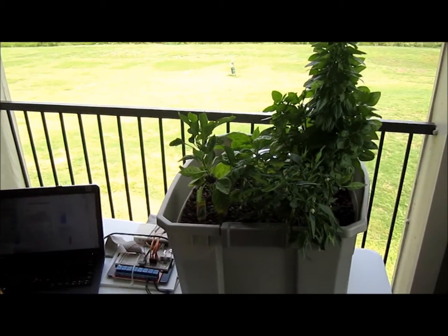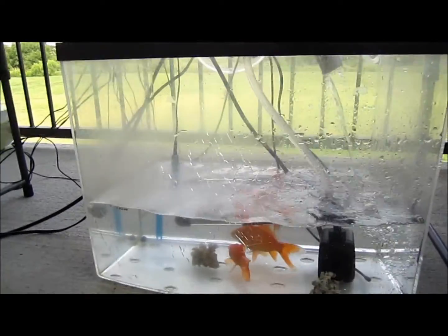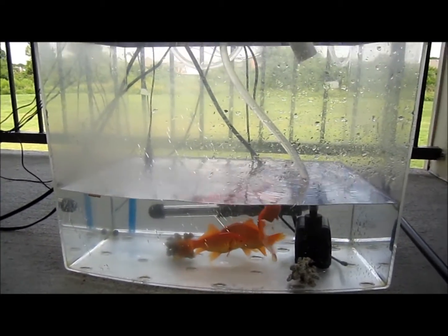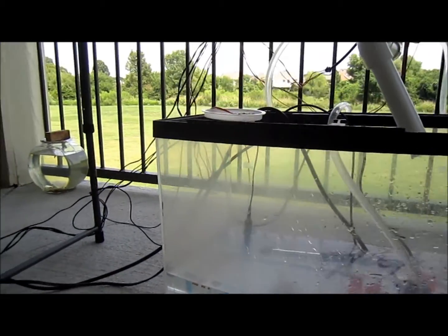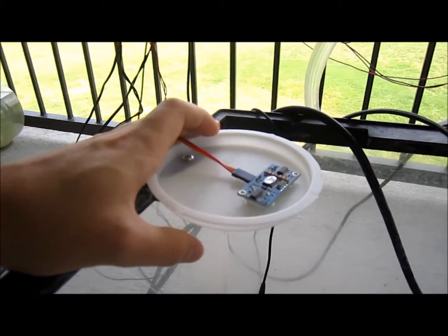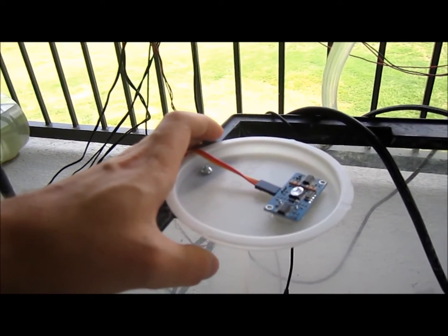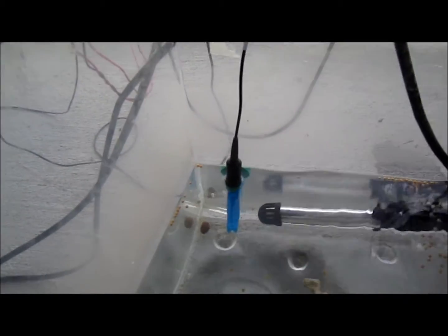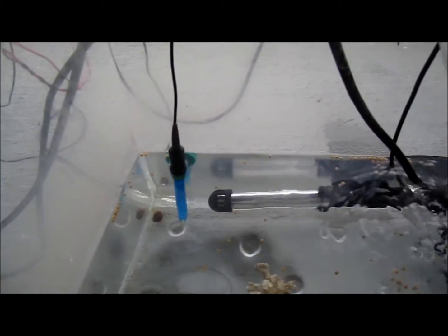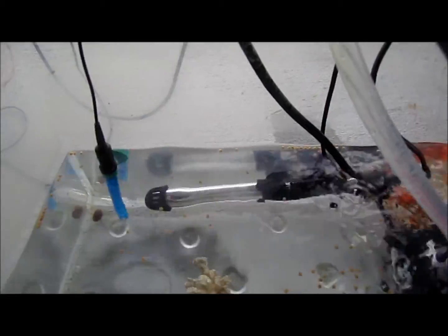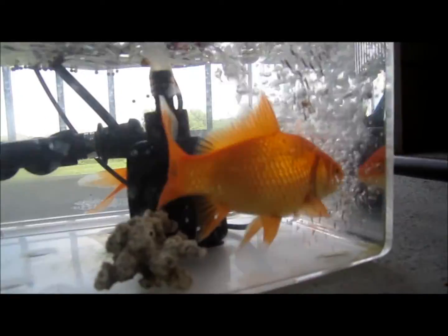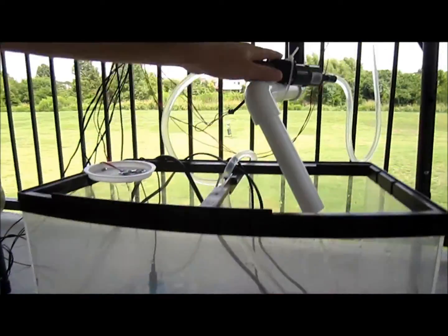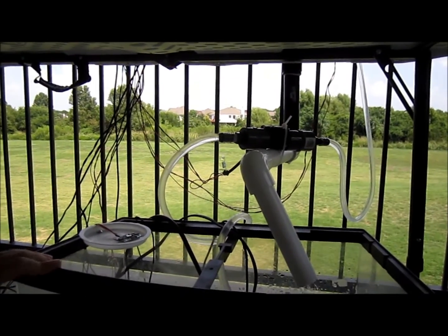Now in addition to the grow bed, we have the fish tank that contains fish. I currently use goldfish. However, you can use tilapia or catfish in your aquaponic setup. The fish tank is wired with various instrumentation. I have here the ultrasonic sensor to measure the water level in the fish tank. Then I have my pH probe to measure the acidity level in the fish tank. I also have my heater to heat up the water in the fish tank if necessary, and a pump to pump the water from the fish tank into the grow bed. In addition, I have a temperature probe right there, as you can see, that monitors the temperature in the fish tank. Finally, I have a flow meter that monitors the flow rate of the water from the fish tank into the grow bed.